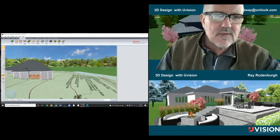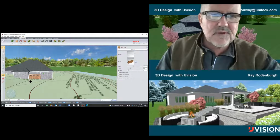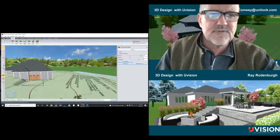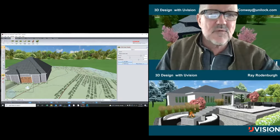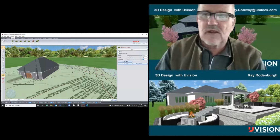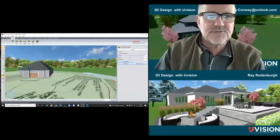Here, you can see you're obviously not going to get your car in there. So you need to have an area grader right here in that area to flatten it into your terrain. You're going to have to just go areas and maybe flatten them out a little bit. It'll jump up 6 feet, but it'll get you level. And that's what you'll do with the area graders. And because you're not carving up the land, you can just go to the taper and get a nice straight line into the garage there.